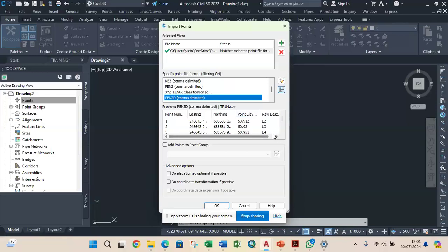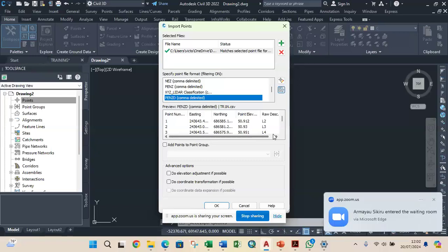So if peradventure I choose the wrong format now, and I import and I click OK to import into the work area, the point will be displayed, but I'll be working on an area that is not properly georeferenced on the work area I'm working on. So those two parameters that I stated earlier are very important: the easting and northing.